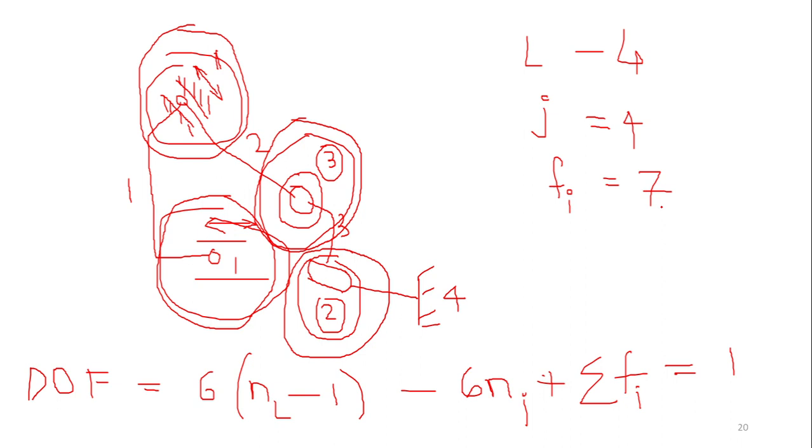So the first one is translation, which comes under 1 degree of freedom. The second joint's degrees of freedom is 1. For this spheric joint, 3 degrees of freedom. And the fourth one is cylindric, considered 2, we have 2 there.